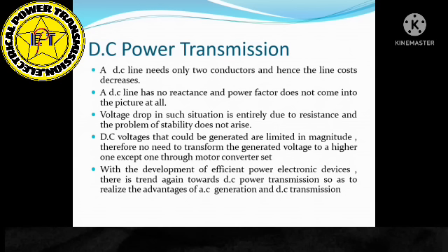So when you are transmitting power through DC transmission lines, the frequency does not exist, so your XL is equal to 0. So your impedance is reduced as compared to the higher value of impedance in AC transmission line. Higher the impedance, higher will be the voltage drop. So dear student, number 3, when your impedance is reduced, the voltage drop is also reduced.